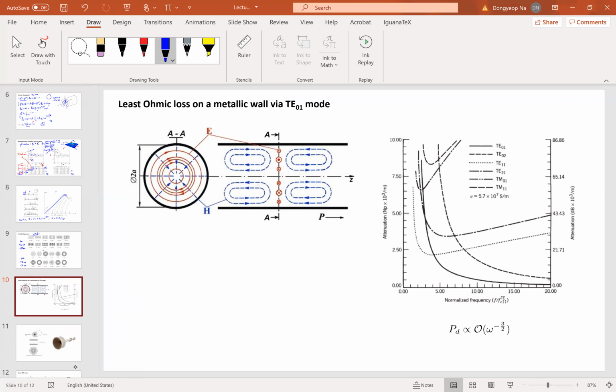That's because if we are operating a very high power signal, and we use a transmission line involving some dielectric material, this dielectric material has the voltage breakdown due to the high power, so we need to use the air, which has a very high threshold of the voltage breakdown. So we are using this hollow waveguide.